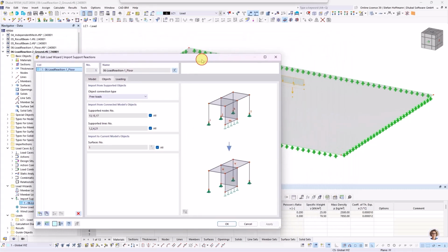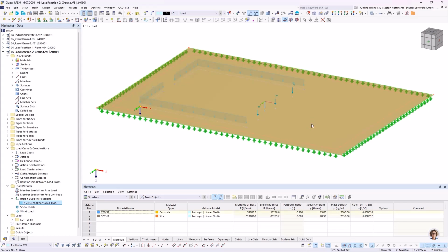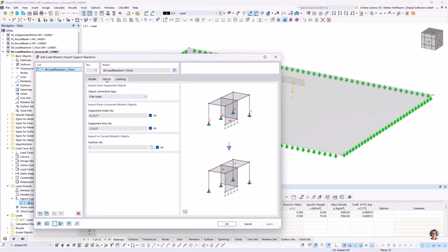So just imagine if you have a floor lying in here and also define a second surface, all these forces will penetrate into the global Z direction, whatever they can penetrate. And this may double the load if you have the same surface down below. So if the construct of the part is only standing on one surface, you have to disable the all check and assign these loads to the corresponding surface.